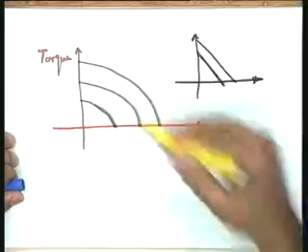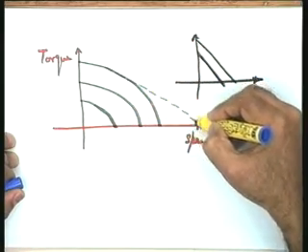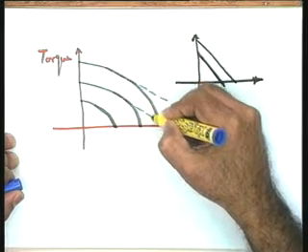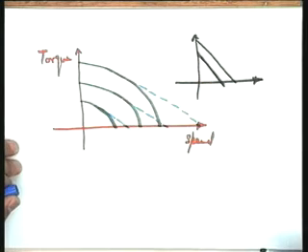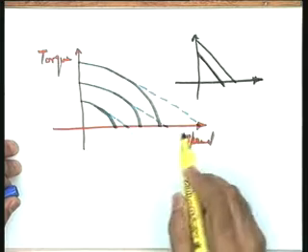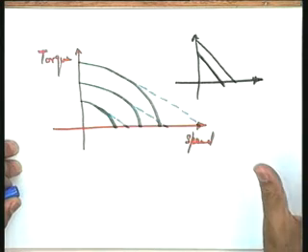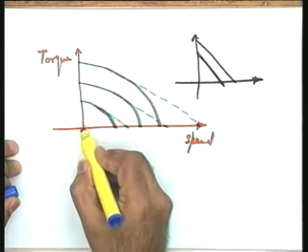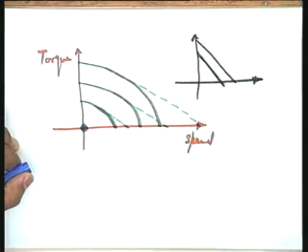So in this particular case, if I linearize the AC motor characteristics, a linear curve appears like this. But what should be the region of validity of this? Fortunately, AC motors in position control systems are quite useful. The reason being, your normal operating point is this. Please see, in a position control system, what is the steady state position? The steady state position means speed is equal to 0.